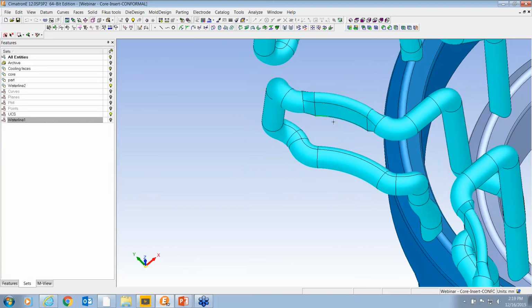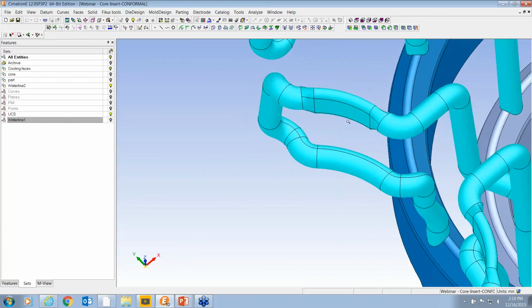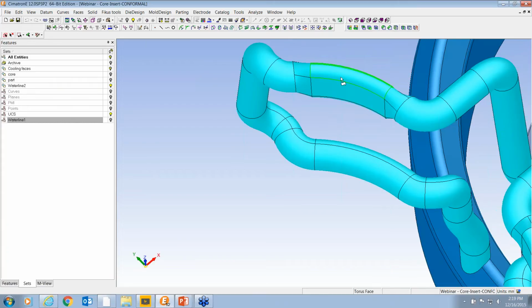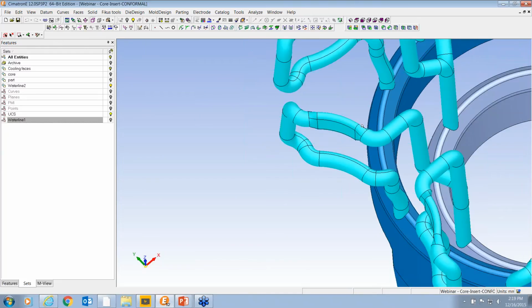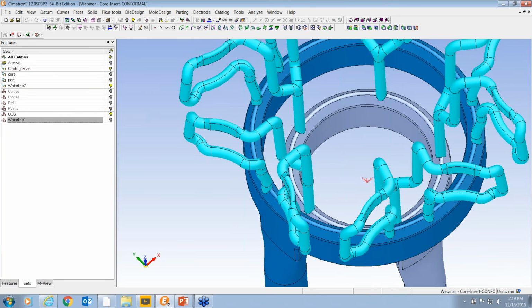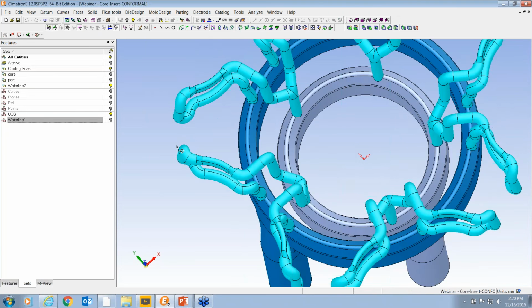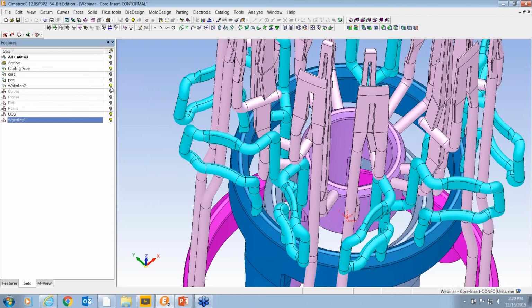But right here, in order to get between a couple of different mold features, it had to be narrowed. Well, when narrowing it, we also elongated it. The idea again is keeping that constant cross-section. Along the way too, you see these transitions. Now, it's nice to keep it nice and smooth, tangent to tangent transition if possible. The most important thing about this isn't so much perfect tangency, but that we're avoiding sharp corners. We don't want to have sharp corners anywhere because we want to avoid cracking in the core. So that's an interesting looking path, isn't it? A little bit involved in creating that. But also, the curvature shows how it's staying conformal to the shape of the coring.